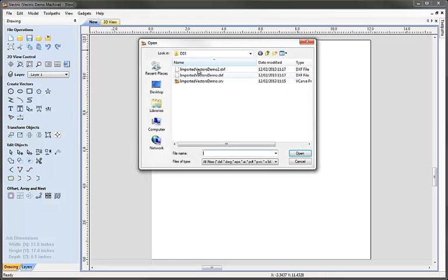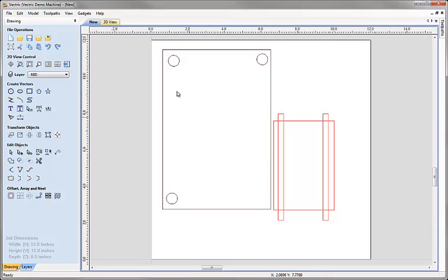And if we use this method, we can choose the same file we had in the initial discussion, but bring the data into our already sized job, as you can see, and the positions of the items are maintained. But this time we've created the job size ourselves rather than have the software work out a minimum bounding region. So that can be very useful if you want to bring in designs that you've created that are correctly located already relative to the job that you're already working on. When you import those vectors through this method, their positions will be maintained and they will be brought into the job as you've already created it.